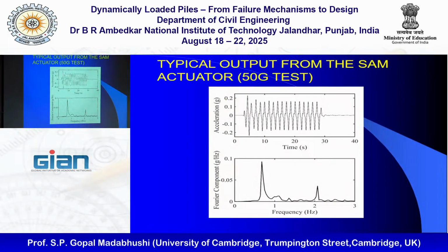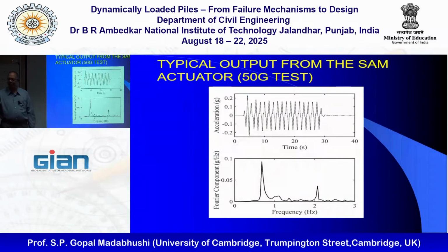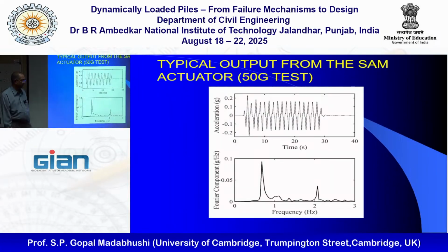So finally, here. So this is very clean sine wave motion. It's a mechanical actuator. And if you do the fast Fourier transform of that, you can see it's produced at about 0.8 hertz prototype scale. It got concentrated energy. So sine waves have that nice feature that you can have all the energy at one frequency. And then once you apply this, you can see how your soil model, structure model is changing. What is the frequency response for that?